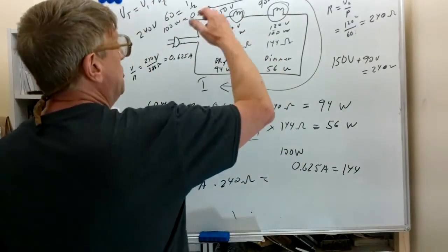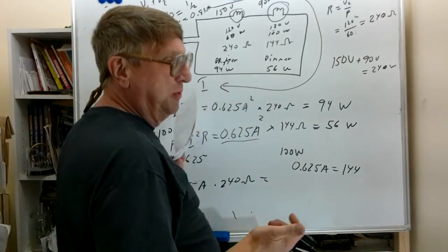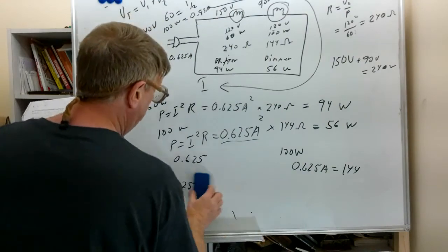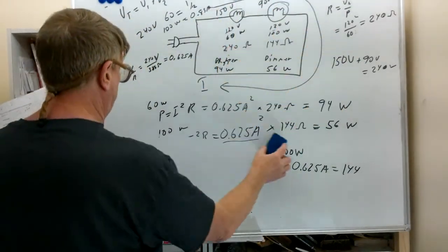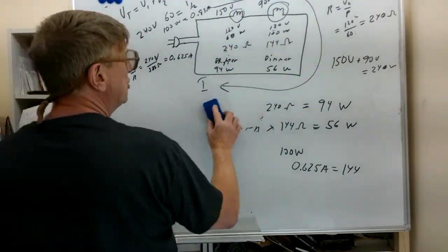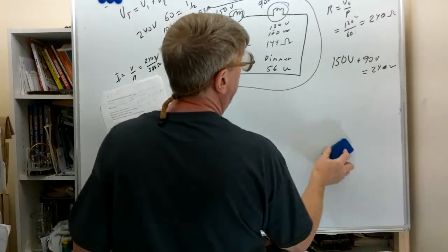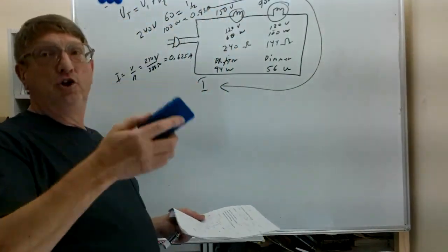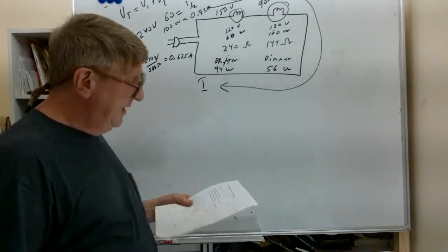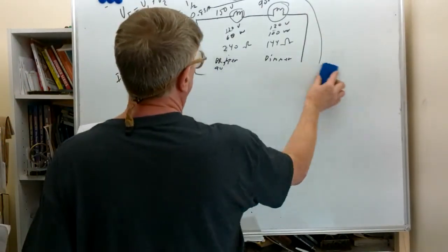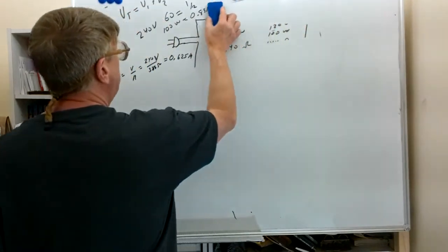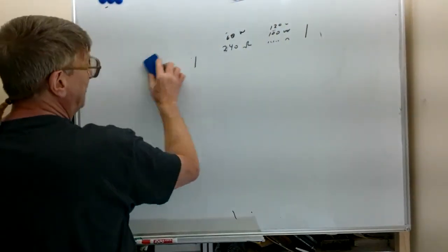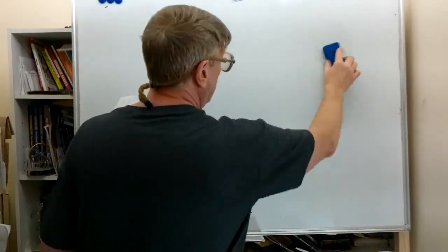What would normally be the brighter bulb runs dimmer. So in a series circuit like this, your loads need to be designed for the same current, because current in a loop is the same everywhere. And in the case of these two light bulbs, they're not designed for the same current, and things don't work out so well.